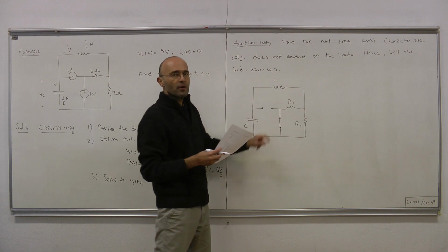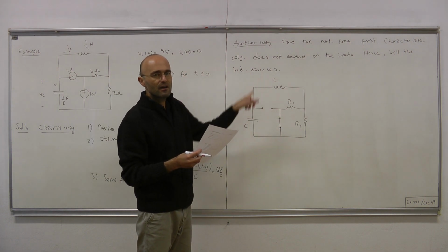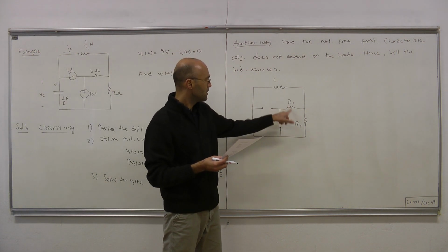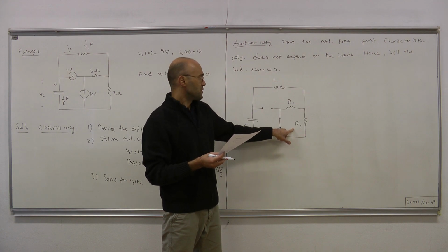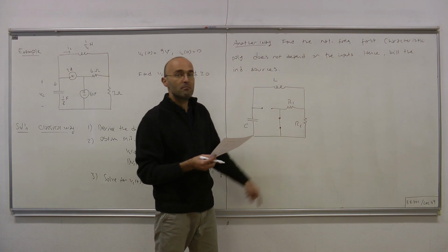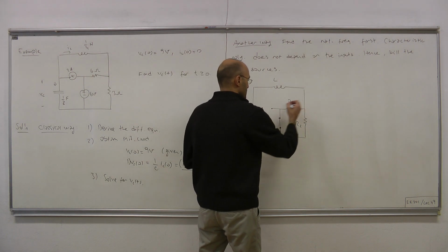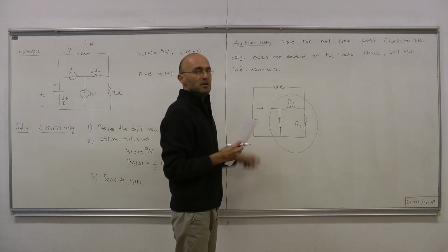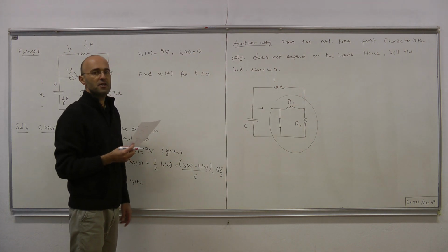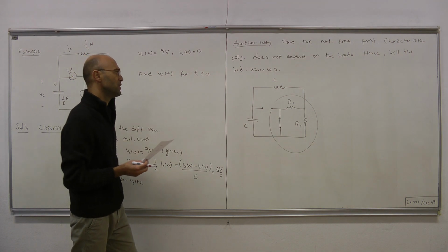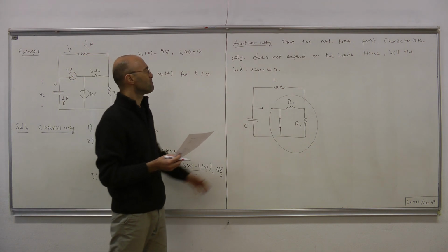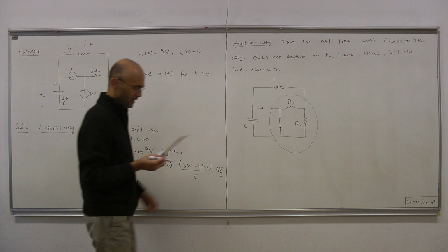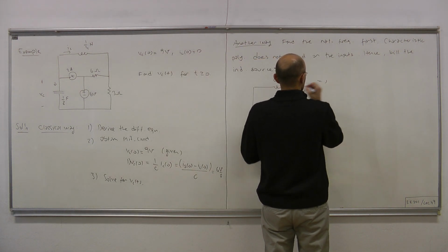Now, one nice thing about this circuit is that it has a topology that we're already familiar with. If you replace these two resistors by the effective resistor, note that they appear in parallel, so we can do that. If you replace this by a single resistor, then everything becomes in series with one another, and we have the series RLC topology, for which we know the differential equation. Therefore, we can obtain natural frequencies easily by killing the sources for this example. So this yields